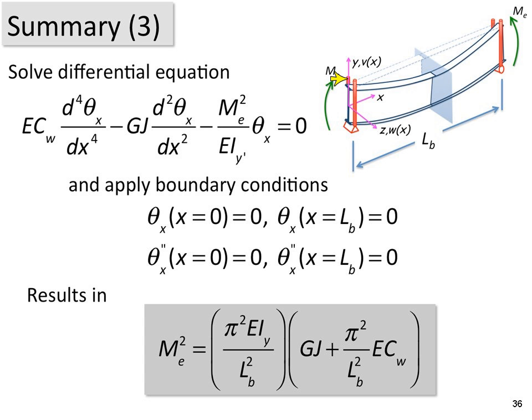So we know that we've got a pin here in the minor axis at each end. That was the second derivative of w with respect to x, and we showed that it was directly proportional to this theta of x. So we've got our boundary conditions at each end. Substitute those into the solution of our differential equation, and this is what pops out.